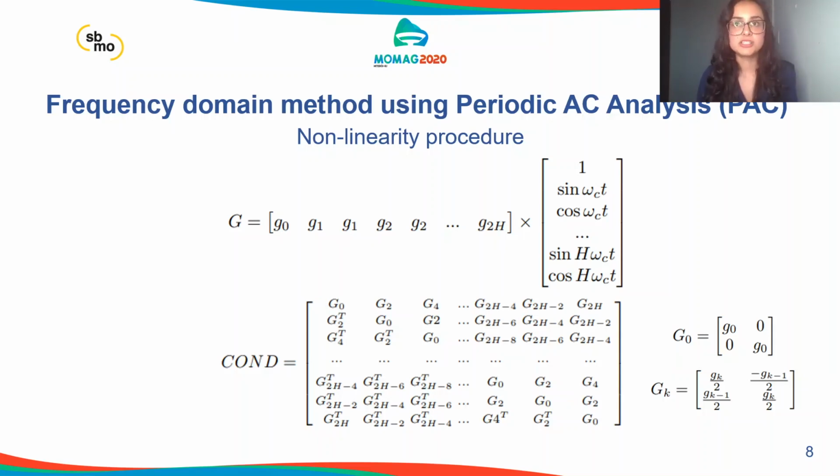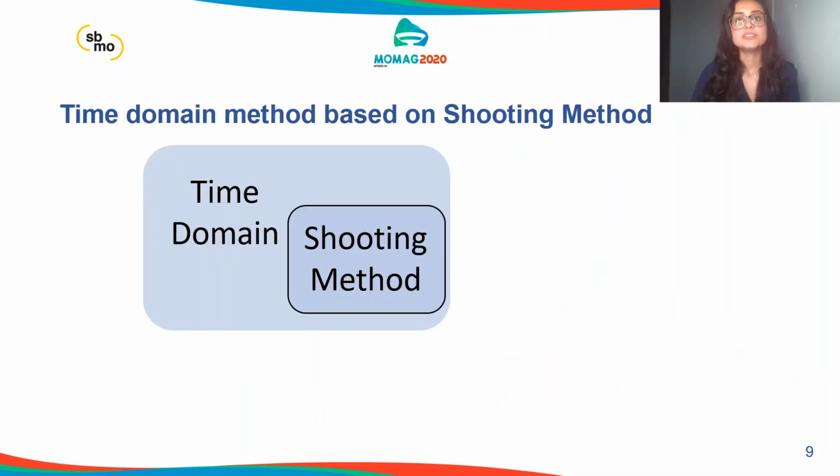Lastly, for simulation with high reconfigurability in the amplitudes of harmonic sources without changing the rest of the circuit and the large signal sources, the PAC method is indicated. The shooting method is used for solving boundary and initial value problems. It is a numerical procedure based on time domain analysis.